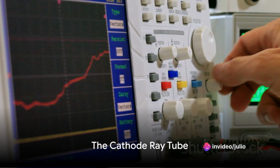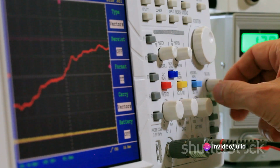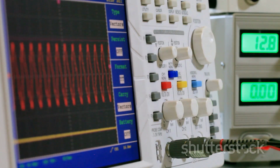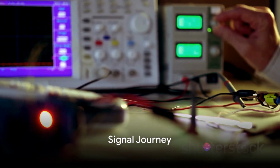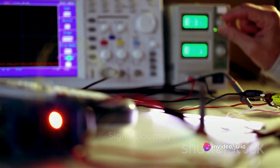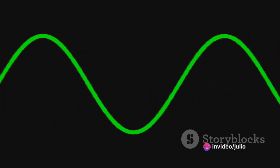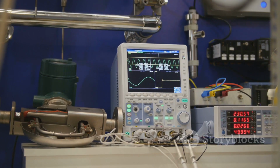The heart of an oscilloscope is the cathode ray tube, or CRT. It's a complex vacuum tube where electrons are shot towards a phosphorescent screen. These electrons, when hitting the screen, produce tiny spots of light. The journey of the signal begins at the input jack, where it gets amplified. The amplified signal then travels to the vertical deflection plates. These plates, when charged, cause the electron beam to move vertically up or down.